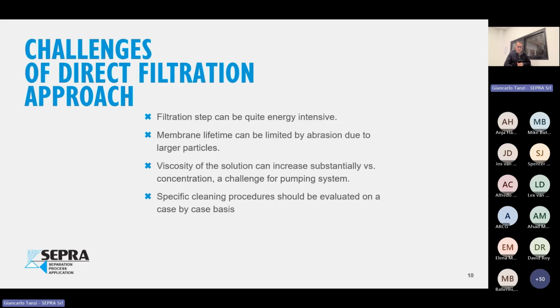Because of the type of pump and the type of mechanical seal that we are using. And again, normally in this tubular membrane application, we are not really worried about the membrane selection. A good quality centrifugal pump will do the job for MBR. Here, not really. Here you need to be cautious in how you select the pump.